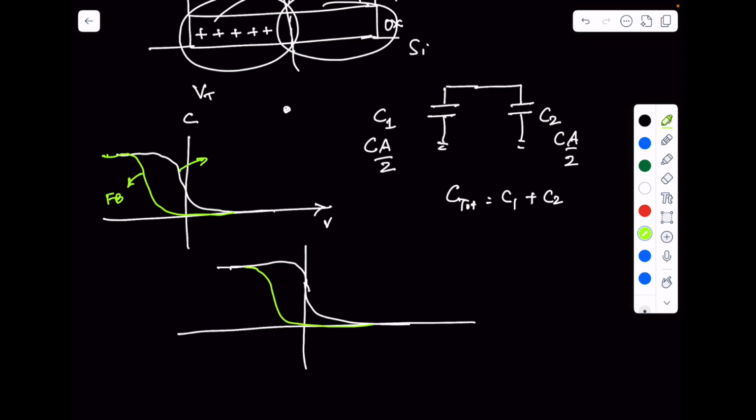So what's going to happen is, if I now draw it in red, you're going to have a sum here, and then it begins to fall, then again a flat, and then it begins to fall, right? So you're going to have two steps in the CV, primarily because one CV starts off earlier and then the second CV catches on, and eventually you're looking at a CV curve which looks something like this. So again, there's nothing complicated, just remember what the flat band does.